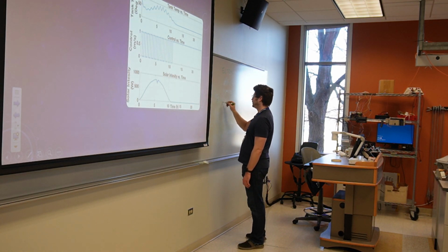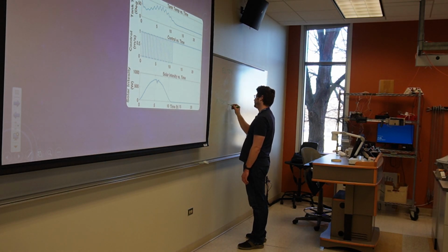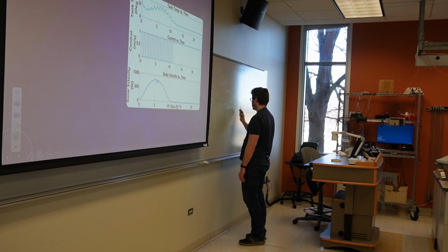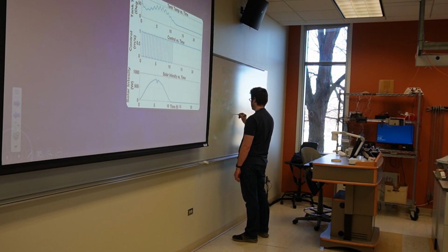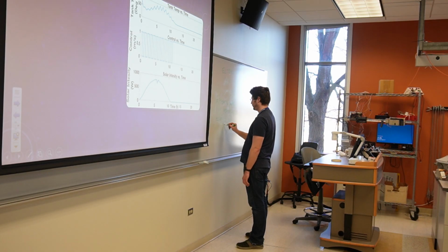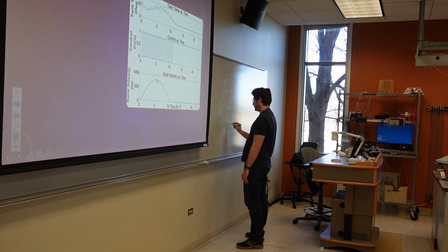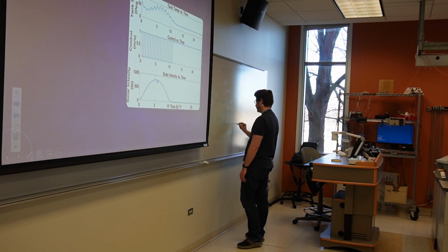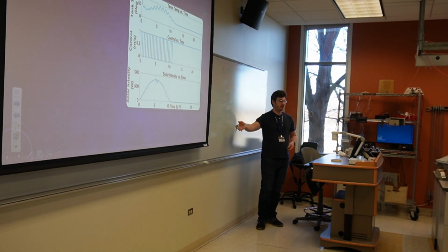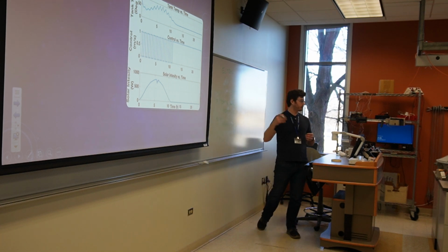If temp is less than set point, then heater is on, or true. Else heater is false. Okay. If we're not where we want to be, try to get there. If we are where we want to be, stop. Bang-bang control, on-off control.